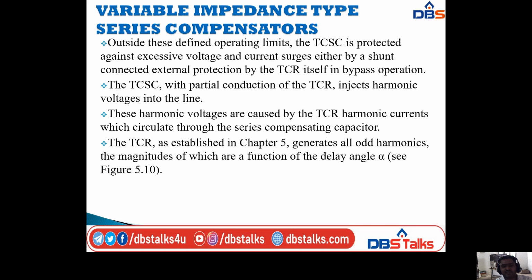Outside these defined operating limits, the TCSC is protected against excessive voltage and current surges either by a shunt connected external protection or by the TCR itself in bypass operation. The TCSC with partial conduction of the TCR injects harmonic voltages into the line.